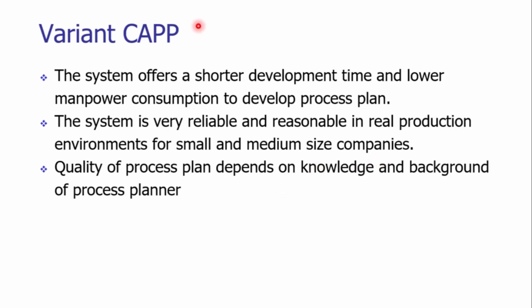These kinds of systems offer shorter development time because we are just retrieving the existing plan. The plan is ready with us, and the manpower consumption is very low. The system just has to search based upon the similarity, the way we search on our regular computers. In a similar way, based upon the geometrical attributes, the system will search for the best plan available, and that would be given to you, and based on that we can develop the new plan based upon the existing plan itself.